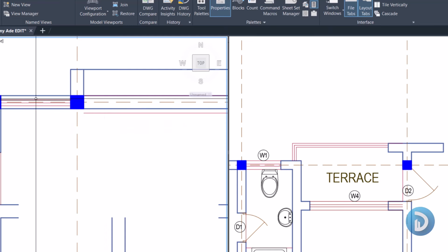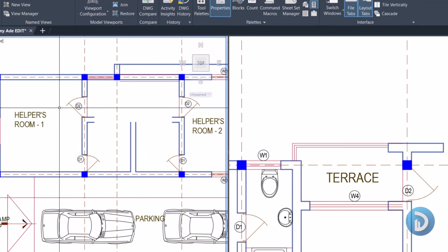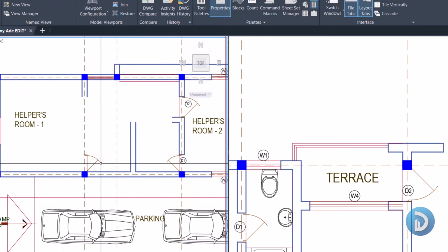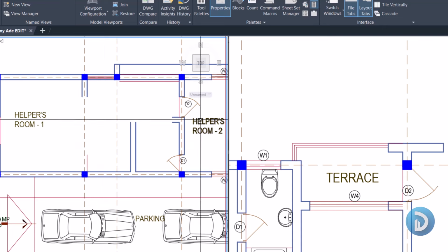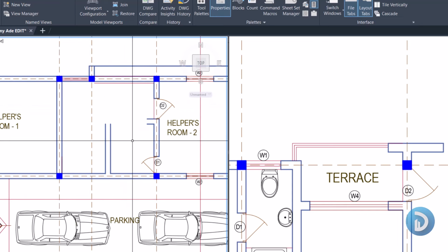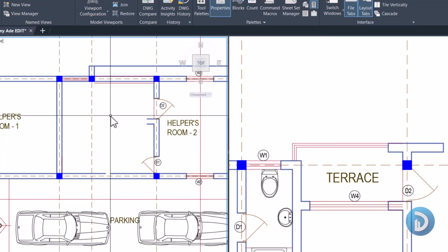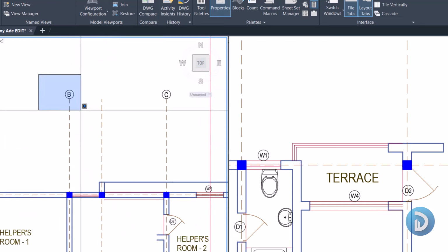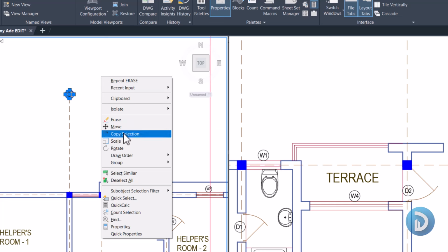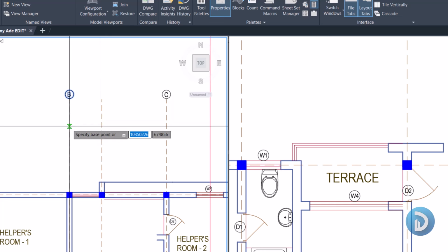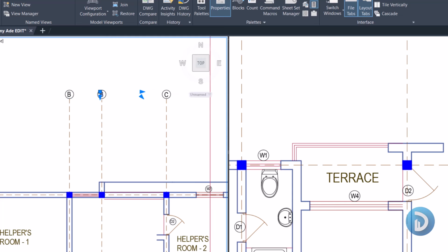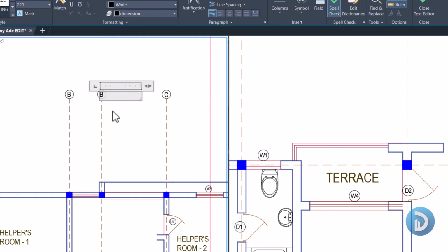here. So why this is advisable is when you get to your Prota structure, you will just get to trace these lines in order to achieve your beam lines. You only have to trace these lines. You don't necessarily have to always go back to your AutoCAD drawing and look at the modifications. You can just draw your beams on this line that you've created from the general arrangement phase. Rename this, and name this newly introduced grid line. So we'll call this B asterisk.